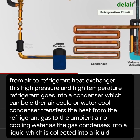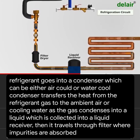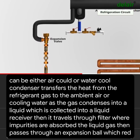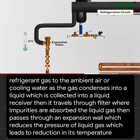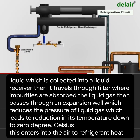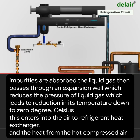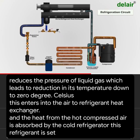Then it travels through a filter where impurities are absorbed. The liquid gas then passes through an expansion valve, which reduces the pressure of the liquid gas, which leads to a reduction in its temperature down to 0 degrees Celsius. This enters into the air-to-refrigerant heat exchanger, and the heat from the hot compressed air is absorbed by the cold refrigerant. This refrigerant is sucked by the compressor and the cycle starts over again.